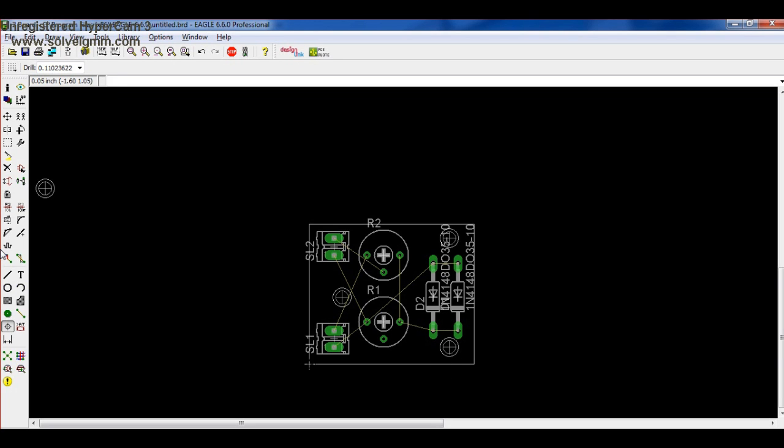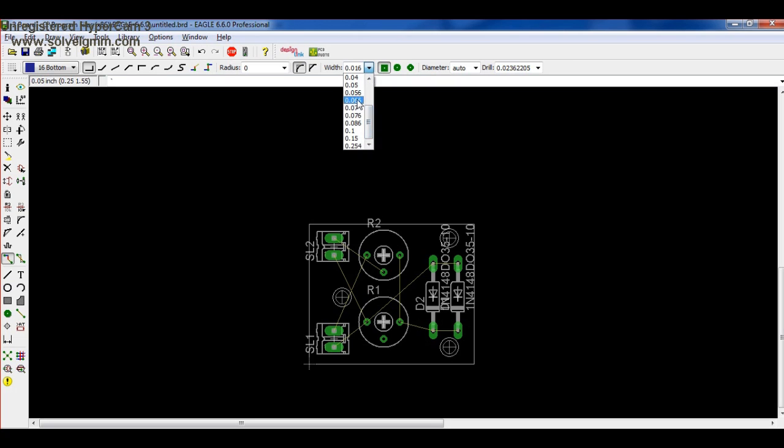Now you can use the route function. Click one pin and then follow the yellow line. That yellow line is your guide to where that pin should be connected. By the way, I use a kind of bent wiring in PCB. It's my style. I don't like full 90-degree copper traces. I want them to be bent. Oops, you can see that I overlapped that drill hole. It's okay to overlap a drill hole as long as you don't overlap another copper trace.